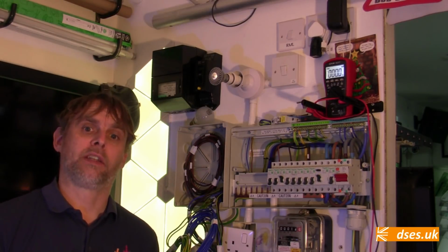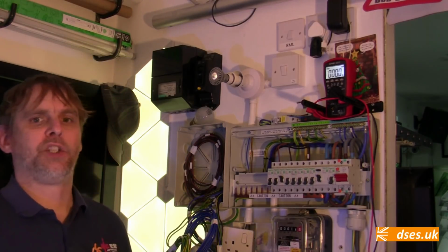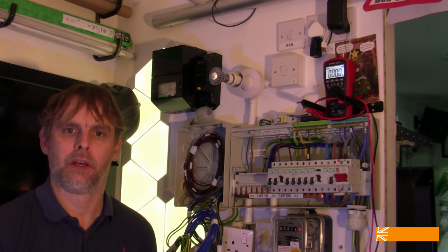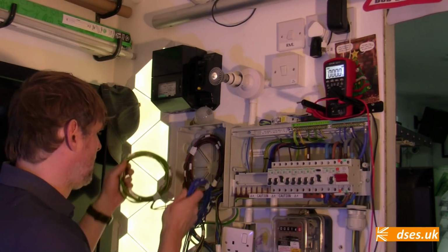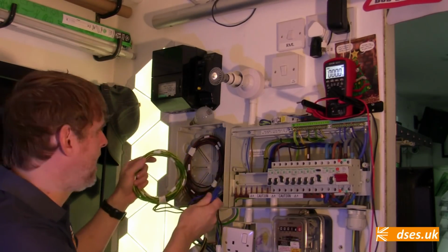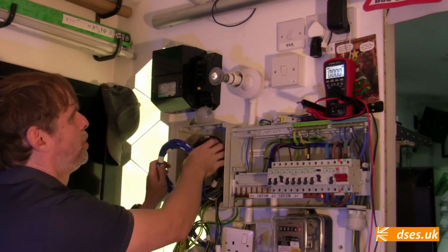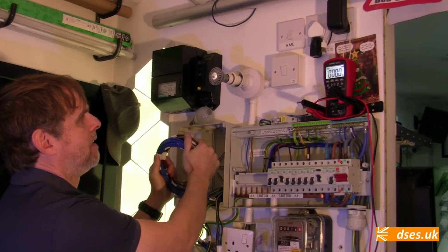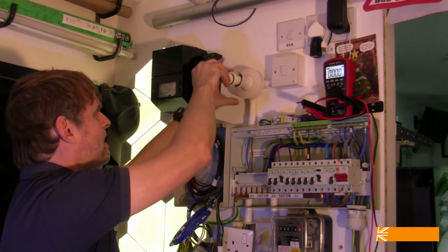How then can we ensure that stray capacitance doesn't affect our LED lighting? Going back to something I said earlier, we can ensure our line and neutral wires are grouped together, i.e. in the same conduit or sheath, as this will null out the electric field. The neutrals of my sockets and lighting circuits and the CPCs are here following a different physical path to the line wiring, but if I bring the neutral close to the line wiring, you can hopefully see on camera that as I get them together the light is physically dimming a little. Let's connect to the voltmeter, shall we, and have a closer look at quite what effect it's happening.